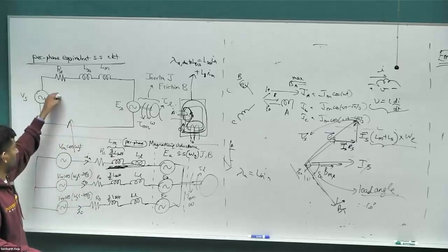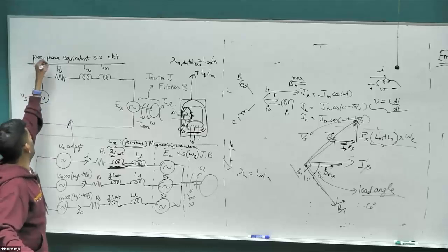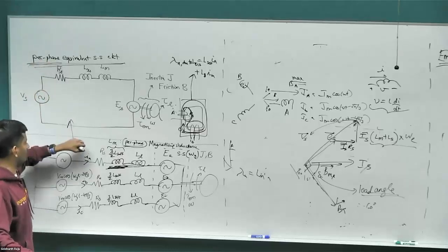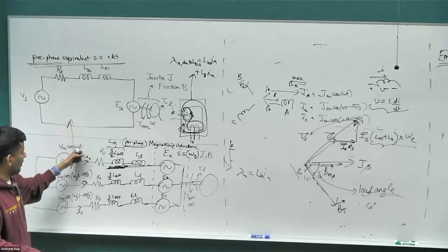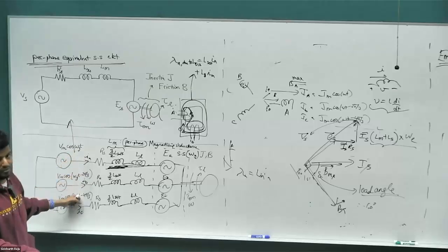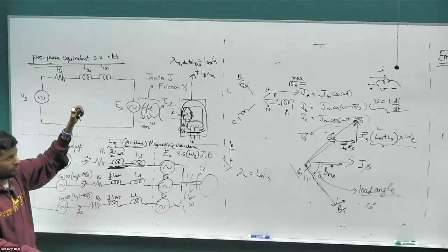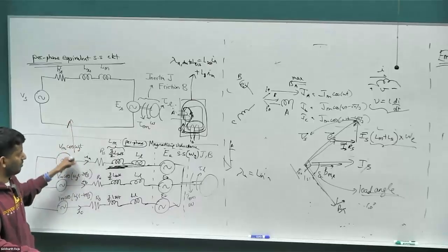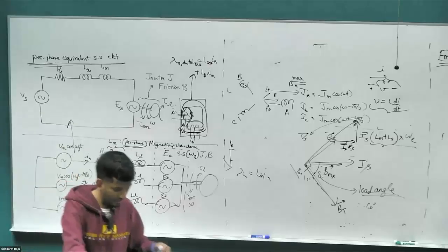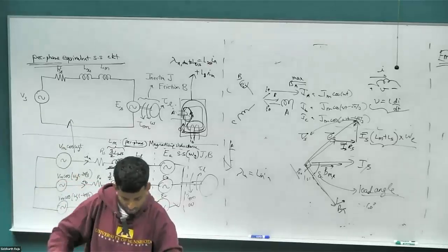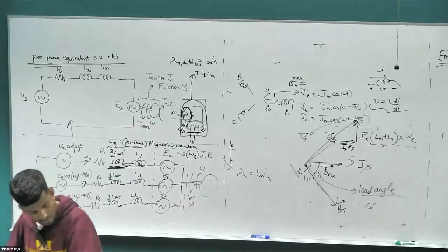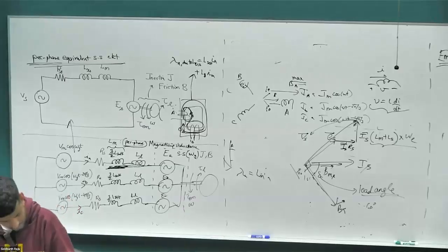Going from a three-phase system to a one-phase system, the per-phase equivalent, is only possible if there is steady state. If it's not at steady state, if I give you the A-phase current, you can't tell me what the B and C phase currents are going to be, because there's going to be an exponential component associated with it as well, which you cannot determine by just knowing one phase current component. With that, let me just take 1 more minute to show you the presentation and then run the hardware. Those of you who have to leave, that's absolutely fine.